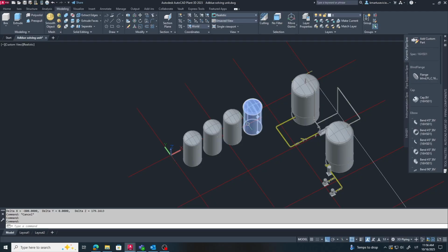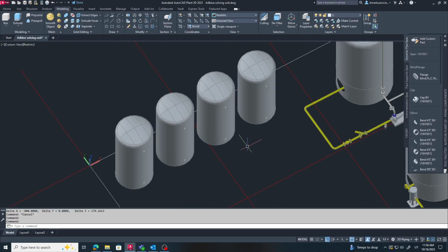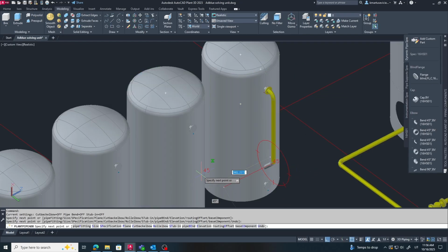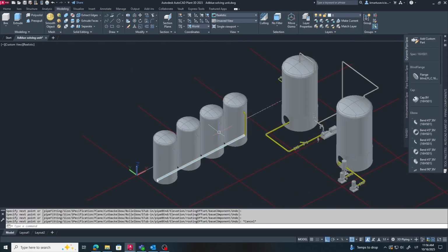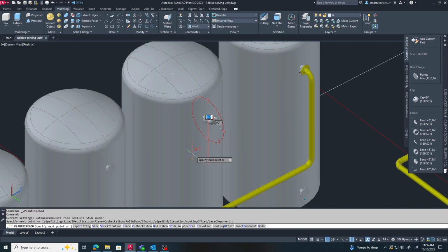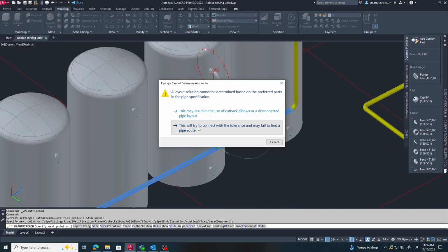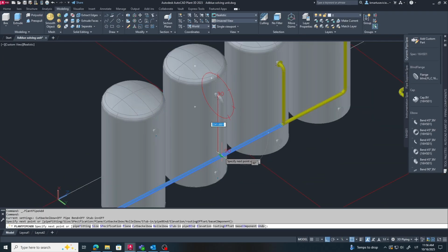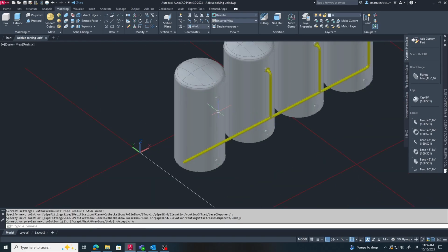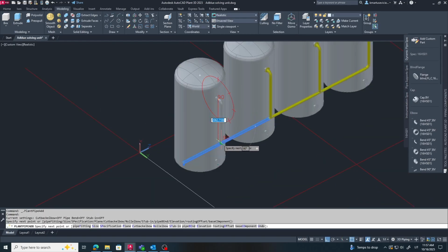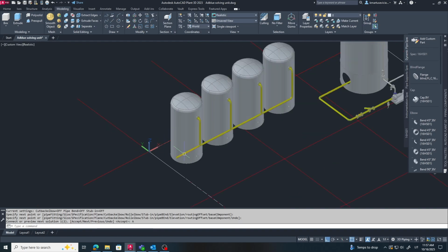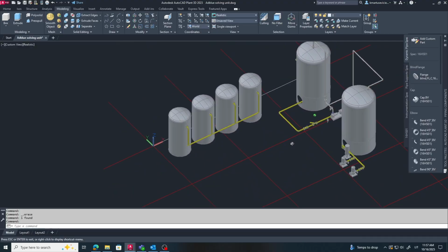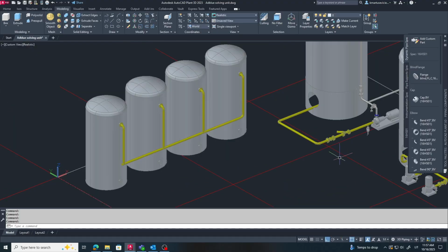All vessels are now in place, so the next step is to create our filling collector. The idea is simple. We will bring all 4 vessel fill lines into one common collector pipe. This makes the filling process easier, cleaner, and more organized. From one main line, we can distribute product into any vessel we want. In real life, this also helps to reduce the number of valves, pipe spools, and welding work. It also looks cleaner in 3D model and is easier to control during operation. So now let's start routing this collector and connecting our fill nozzles to it.